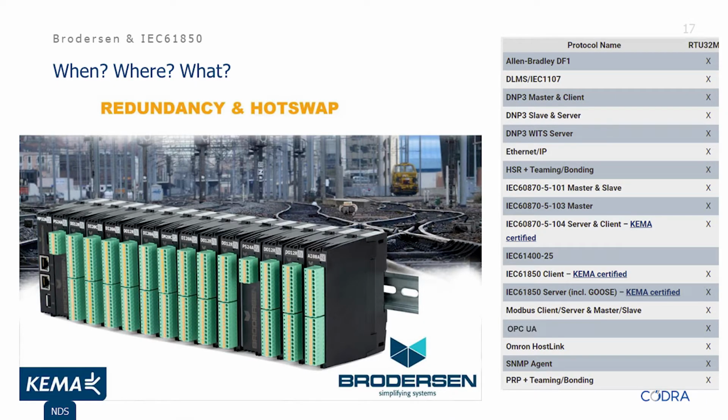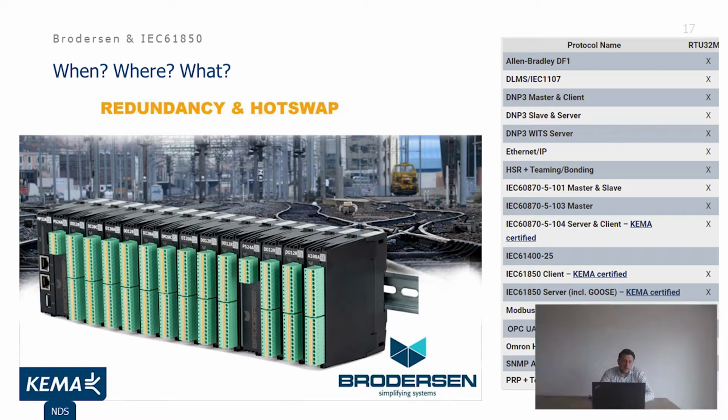Yeah, so where do we, at Brodersen, see an increased interest in the utilization of IEC 61850 in our RTUs? Well, a common scenario is when revamping a substation with PLCs or other devices which do not support the IEC 61850 protocol. Then the RTU can easily provide the needed data to the Scada host using either IEC 61850 or OPC UA. It is just acting as a gateway for the Scada host.